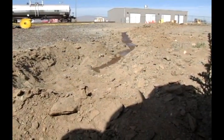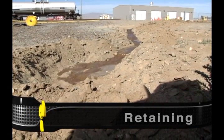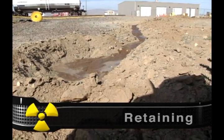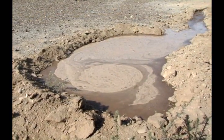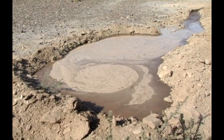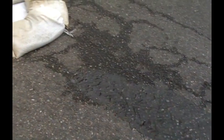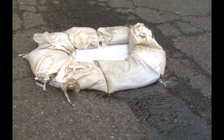Retaining temporarily confines the product in an area where it can later be absorbed or vacuumed up after dilution or neutralization. Some retention methods involve creating a basin to capture flowing product. Other retaining operations may include securing a storm drain or manhole cover from the spilled product.